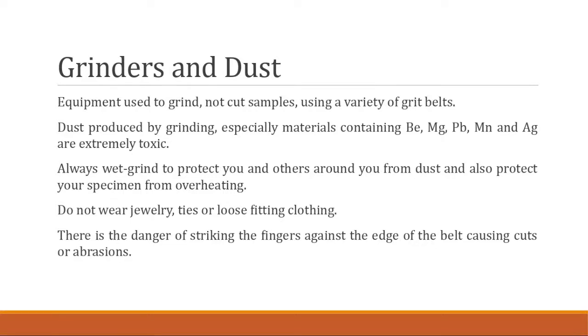Do not wear jewelry, ties, or loose-fitting clothing, because if something rotating grabs hold of any of that, it just spells disaster. If you're going to be wearing a necklace, you can tuck it into your shirt. And of course, you do have the danger of striking your fingers against the edge of a belt, and of course that does cause cuts or abrasions. It happens to the best of us. Hopefully not you guys, even though I think you guys are the best. Just learn from me. Don't do it.